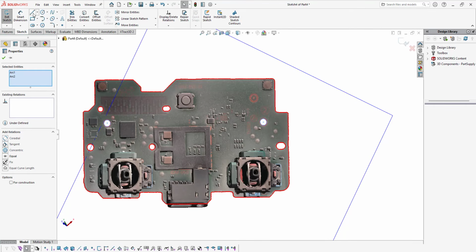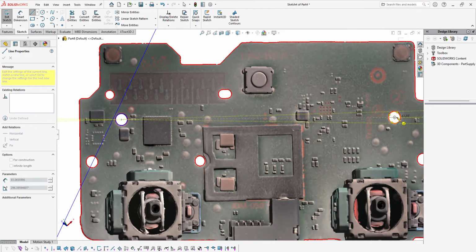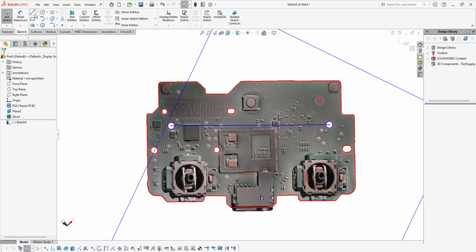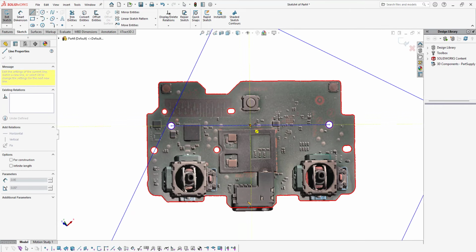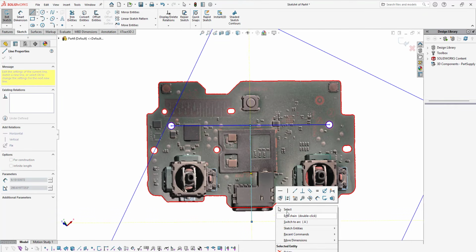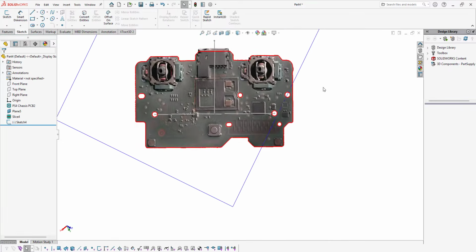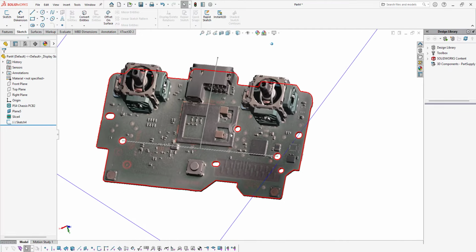Now going back to the SOLIDWORKS sketch toolbar, draw a line from the center to the center. That will give me my x-axis. Then picking off the midpoint of that line like that, perpendicular gives me my other axis. And that's all my sketch geometry created. You can place the coordinate system wherever you choose. It's just that's how I'm going to align this part.